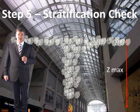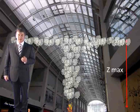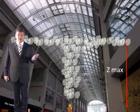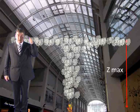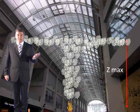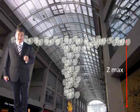So we know how much smoke we've got and how hot it is. Let's move on to step 5, the stratification check. Now in this case, because the clear air height is 24 metres, we need to consider the Z max, in other words the stratification point. We have to make sure it's not going to stratify and not make it to the top or to the ventilators. That's what you've got to work out now, Z max, and this is going to work out whether or not the smoke is likely to make it to the ventilators.